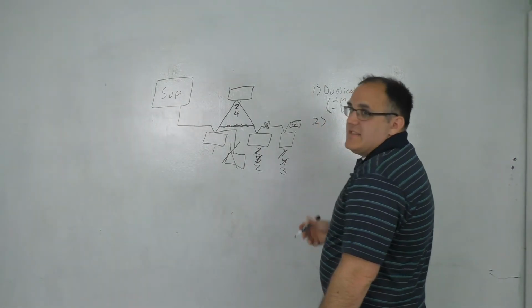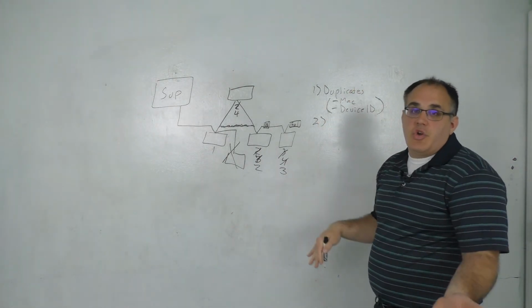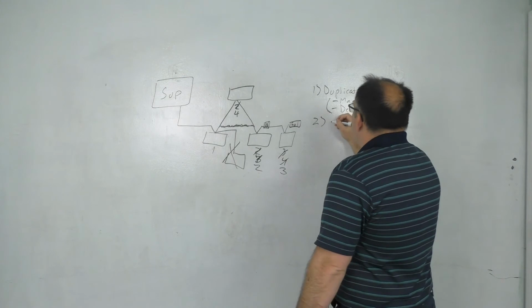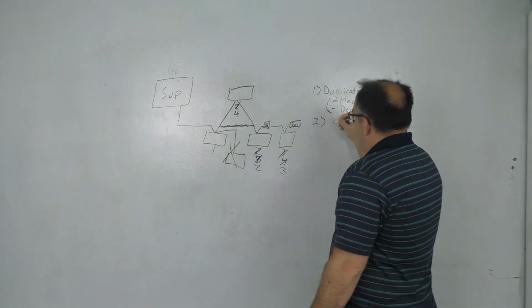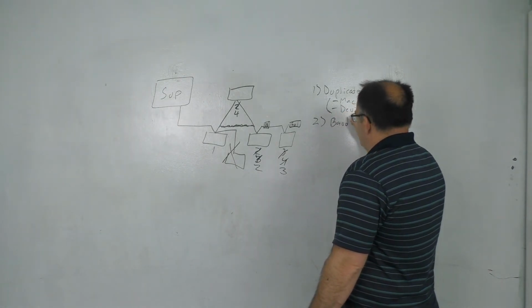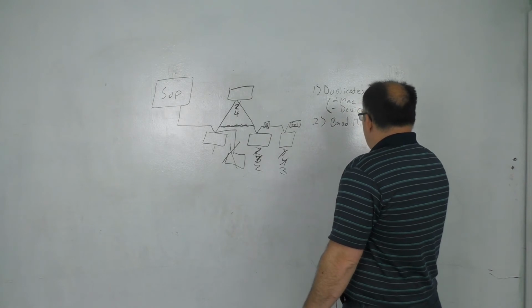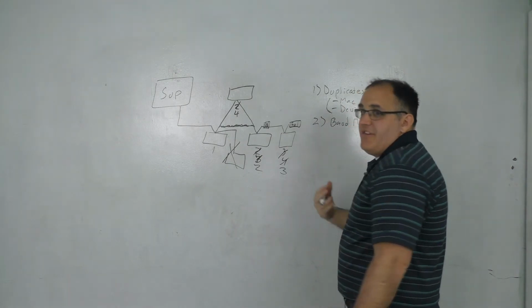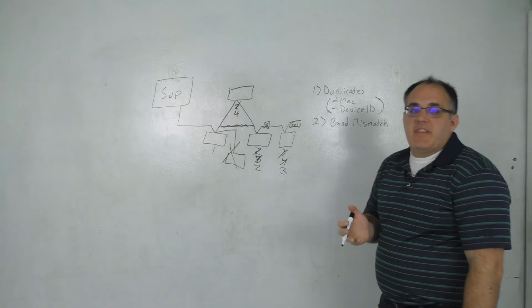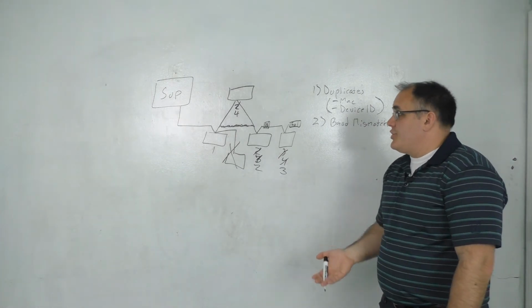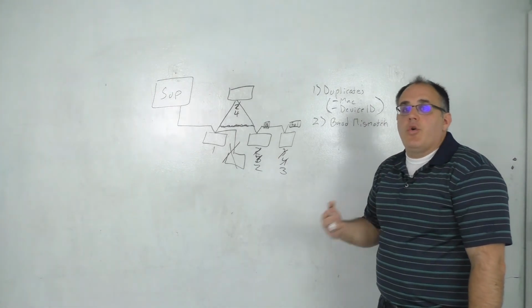It's signified most of the time by the trunk just going down. Another is baud rate mismatch. So you get a BACnet MSTP VFD. It gets started off by the mechanic. The mechanic puts 9600 baud. The rest of your trunk's at 38.4.